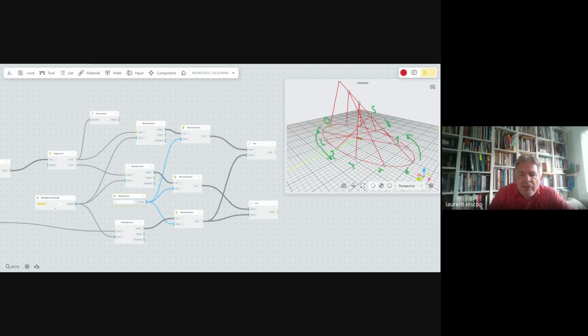And when it connects, the one here on the straight line is trying to get the one on the curve. And number 2 is trying to connect to this one, and so on. So it is twisted. So what we do is say, okay, we've got to reverse the flow of the curve. Instead of turning this way, it will turn this way. So for that, we do a flip. We flip the geometry. And doing that, 0 comes back here, and 1 here, and so on and so forth. And this is how it works now.